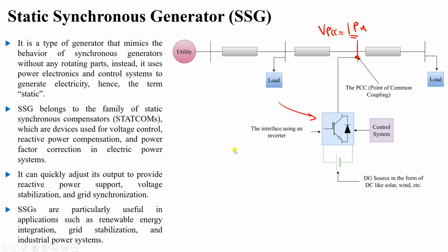I have used a static synchronous generator formed of a rectifier, a DC link capacitor, then an inverter to connect a wave energy resource, one of the devices used to convert wave energy into electrical energy. I integrated it into the power grid using a back-to-back converter, which we will see inside this course.